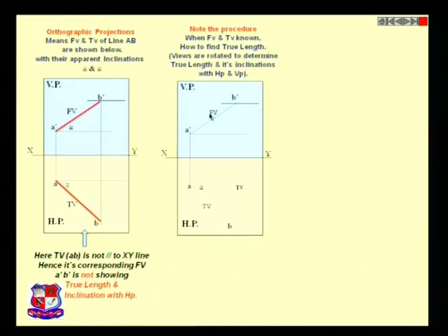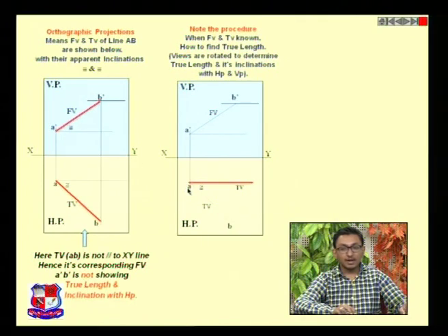This is our top view, this is our front view. We have drawn a line like this. Now, what we have done is taken this arc with radius AB and center at point A, and marked an arc till the line which is parallel to XY but generating from the point A, like this. Now what I am going to do is extend this line to the B dash parallel line. And when I